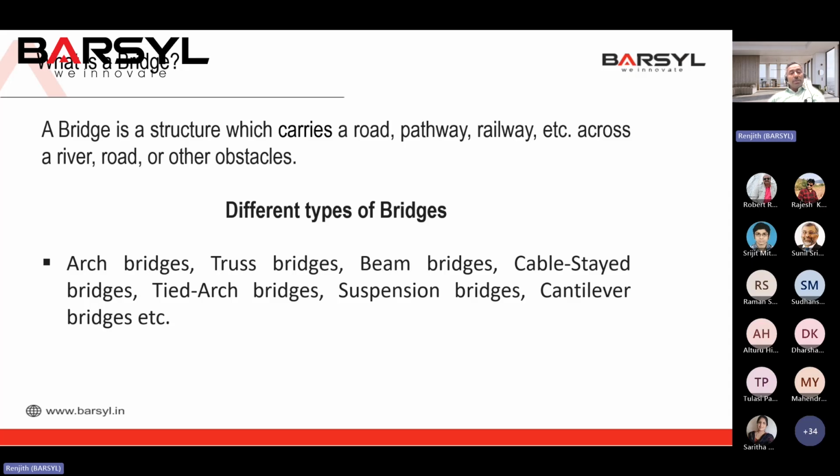railway bridge. In railway bridge also, because we are basically dealing with only railways. So our topic, what I selected is a railway bridge, and for railway bridge also I am limiting my topic to an abutment. Abutment is a structure at the end of the bridge. So you might have seen different types of bridges. At the two ends, the structure which is supporting the span and the embankment is called the abutment. What all comes in between, if there are n number of spans, are called piers. So in bridges, at the end the supports are abutments, and in the middle, all those are piers.